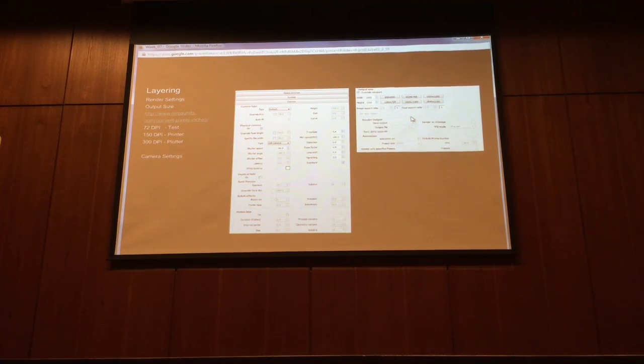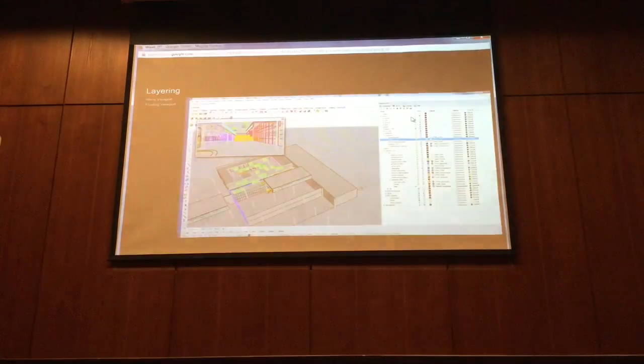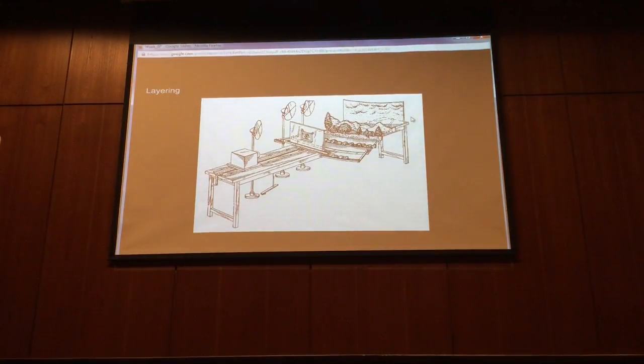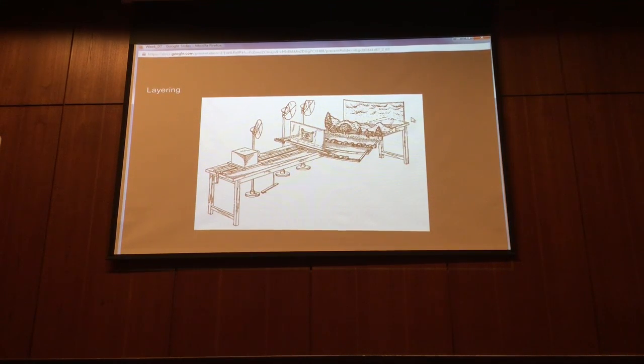All of that is key in any image you're making, understanding that the size you render an image at affects it. And this is what I want to stress from the beginning: when you're trying to render a 300 DPI or 150 DPI image that's 10,000 pixels at its maximum length, you're probably not going to be able to render everything at once.